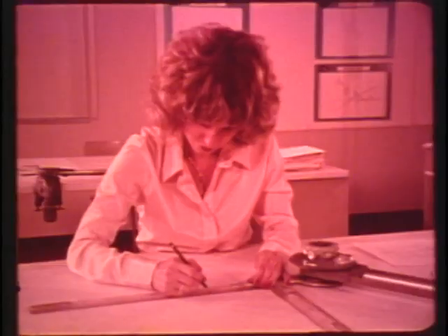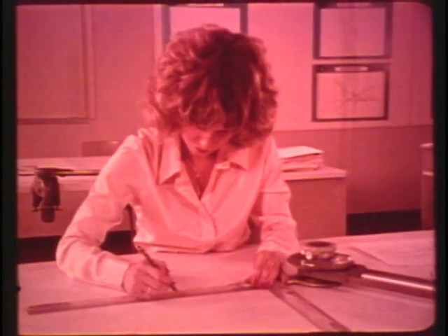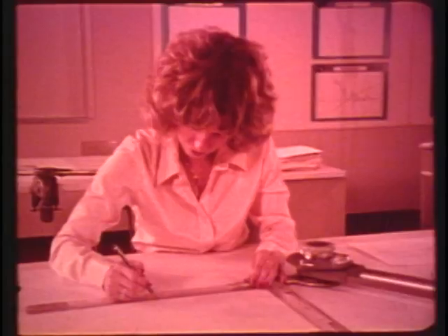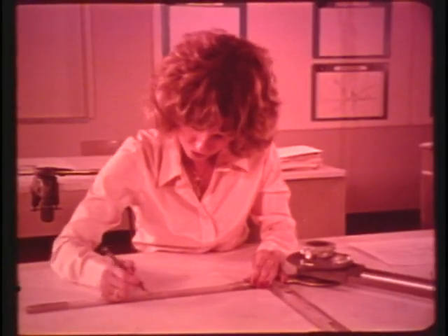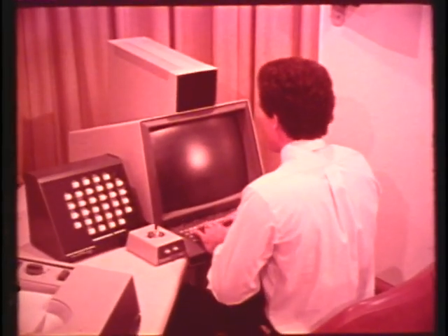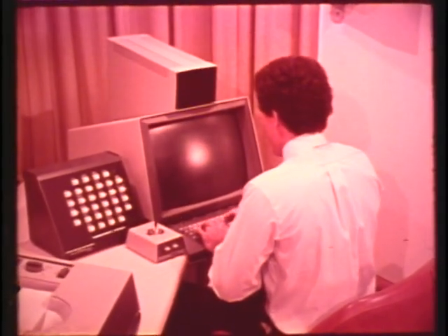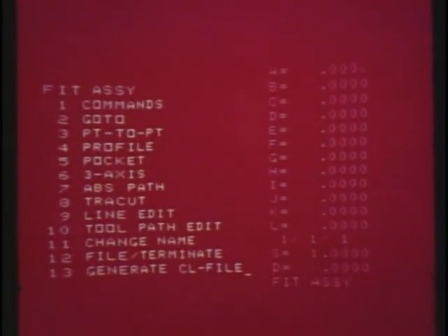But this is just the beginning, for Unigraphics is more than just a drafting tool. It provides capabilities beyond those of the designer draftsman. Unigraphics provides an interface between computer-aided design and computer-aided manufacturing. Using the Unigraphics system, the manufacturing engineer can develop the cutter paths for the numerically controlled machine tool that will produce the part. He has at his command powerful machining capabilities that will automatically generate the tool motions required to machine any designated surface.